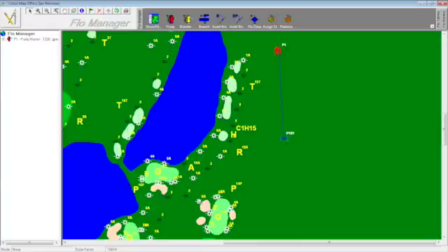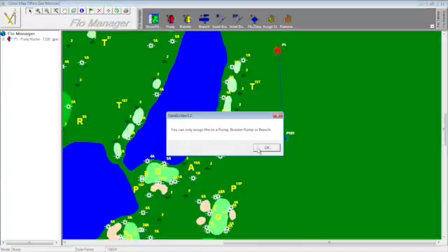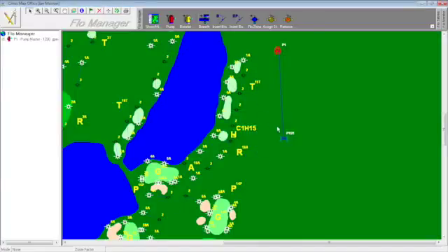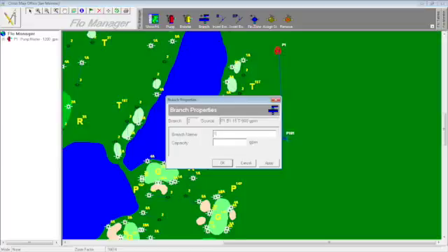Try to add new branches where you know there will be other branches coming off to make it easier to visualize on the map. Continue to add branches to the existing ones, showing all of the same ID features and GPM for that section of pipe. Remember that the software cannot compute loops.